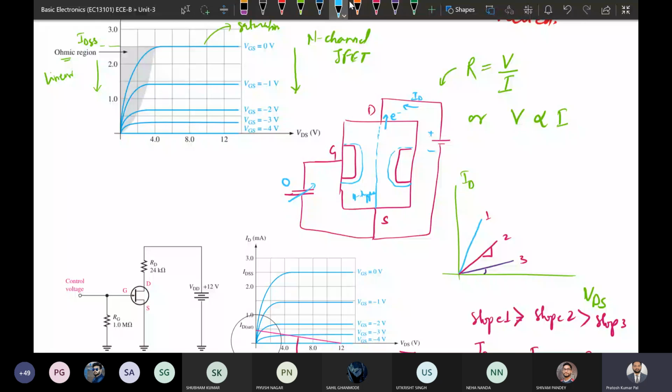So this is behaving like resistance when we have biased it in such a way that it is going to work for the case where VDS is less. Okay, and also if we are going to bias such that the VGS is even higher or even greater, then it will be behaving like a linear region. Okay, so this is the basic concept of FETs or JFET, basically behaving like a variable resistance.